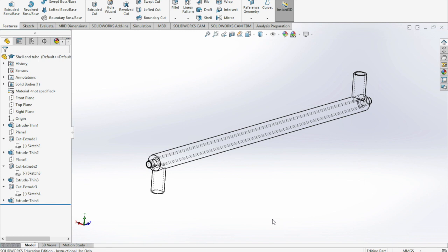You should make sure that the geometry is well defined and well contained. Don't create a shell that has an opening somewhere and is loose. It can happen very easily because the geometry is usually more complicated than what you see, and it can be problematic from time to time.